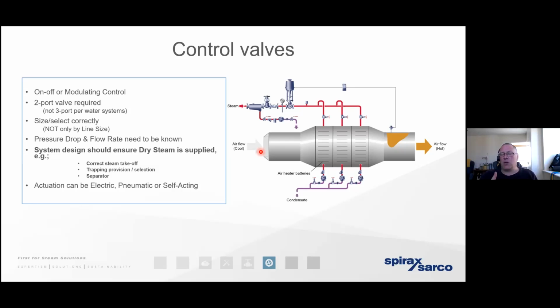And the biggest problems that we come across with control valves are, well, they're either oversized. And if they're oversized, it means that the seats will spend a lot of time operating very closely together, at which point we get a lot of erosion expected because the steam will be moving at a greater velocity. And other problems are, well, those conditioning ancillaries that we've spoken about are quite often overlooked. So of course, we expect to see problems with erosion of control valves at that point. Typical rule of thumb, a well-sized control valve should be approximately 2 pipe sizes smaller than the upstream pipework.